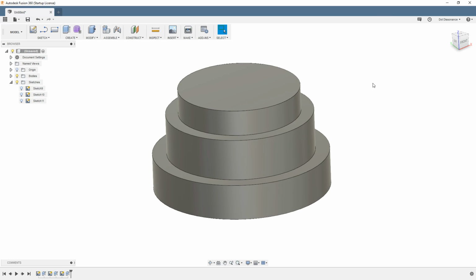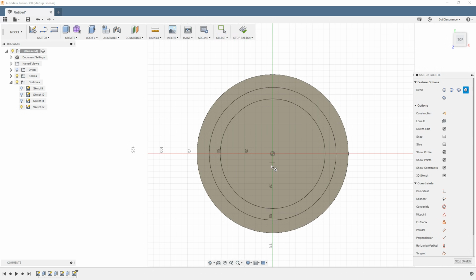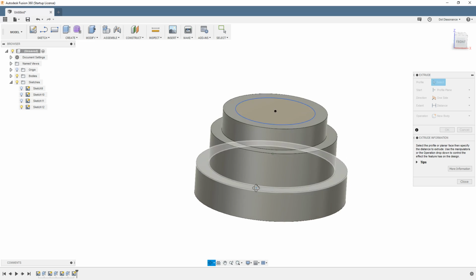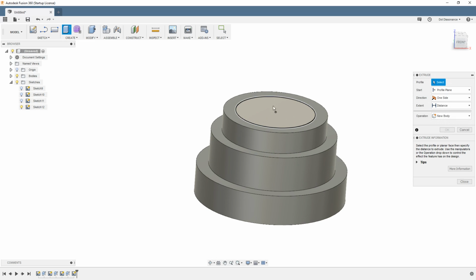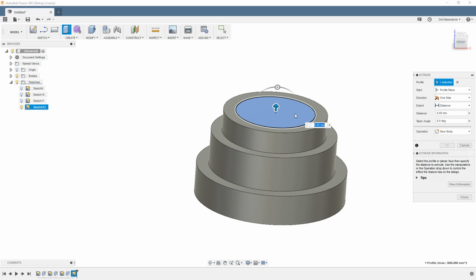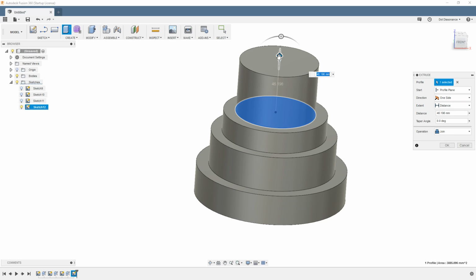Well, that's interesting, but how fun is that going to be? So we pick this, and we go into Sketch, and we'll do another circle, say like that big, and it's still E for extrude. So this is going to be kind of interesting. This is a bit different from the other CAD programs. Here's my extrude, here's my shape, I pick it, and there's my arrow. This is why I was mentioning the arrow. It's kind of convenient to use it. I could just type stuff here, but if I grab it and drag it up, just as you saw, it goes up.